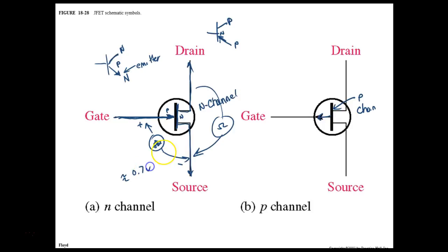because as far as I know, I've never seen these made out of germanium. All I've seen are made out of silicon. And then I should be able to change my polarity, and then I should read whatever your meter reads when it sees a reverse bias junction. And then we could do the same thing here. So we can check these guys out.